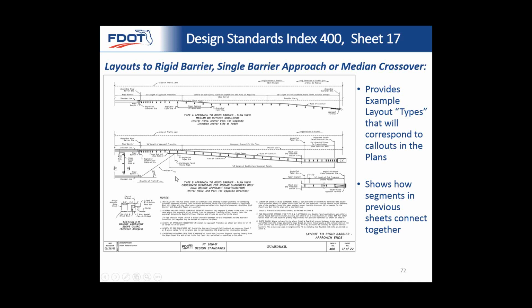And not only that, because you're in the clear zone, coming from left to right, the back of this guardrail is considered a hazard, and it's within the clear zone for these people. So you have to have panels on the back. Now, since we've established that we have panels on both sides, the way to get the shortest run of guardrail is to start tapering across the median.